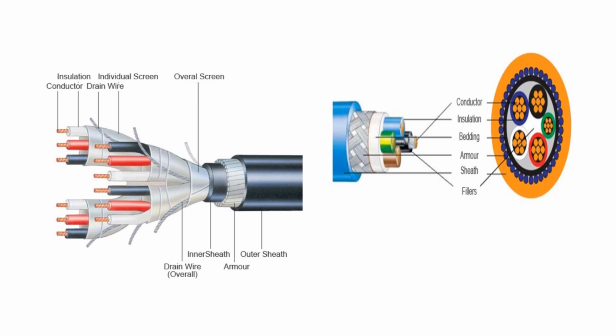If you are a technician always doing these kinds of cable terminations, you will be familiar with all of this: from the outer sheath, cutting it with your cutter, cleaning up, removing all the screen, the individual screen, removing the outer sheath for the insulation and terminations.